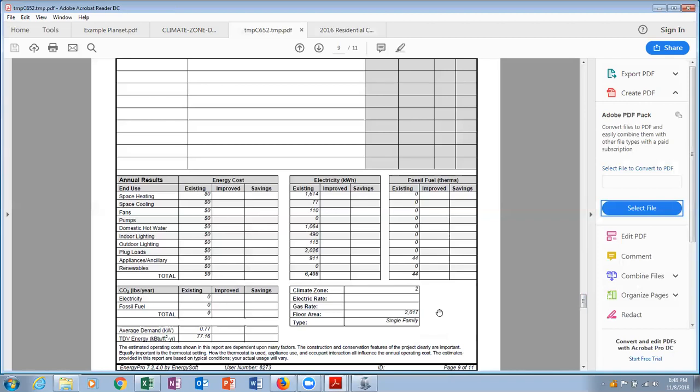So the one thing that I like to get from this document, no matter whether you do it in Res Title 24 performance or Res performance, is a total electricity kilowatt hours per year for the whole house. This is the energy consumption of the house as modeled. And this is a quick way to get an estimate of how much solar you would need or how much energy you consume throughout the year. You could do basic calculations to figure out the kilowatts of your system.